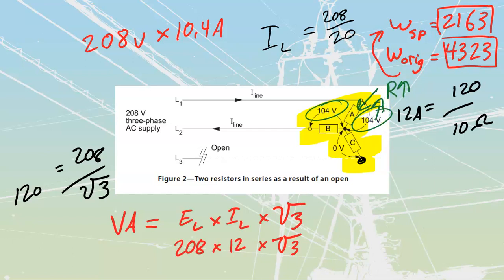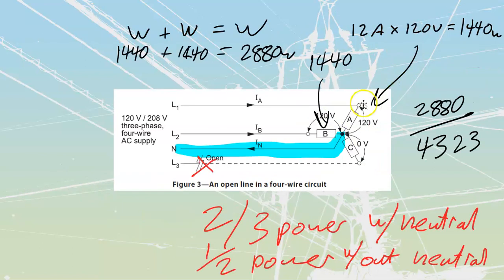In fact, it could be over 120 volts, it could be 150, 170, which on a 120 volt load is not going to be good. Whereas with this type of system, if this one was a higher value of resistance, as long as we've got that neutral connected, it is still going to maintain that 120 volts across it. Safer stabilization of voltage, and stabilization of my system itself.